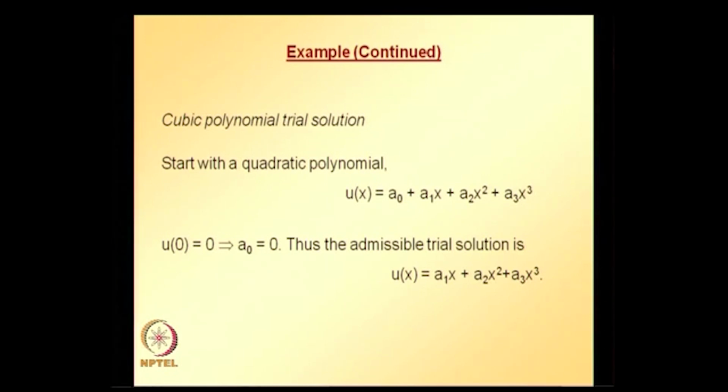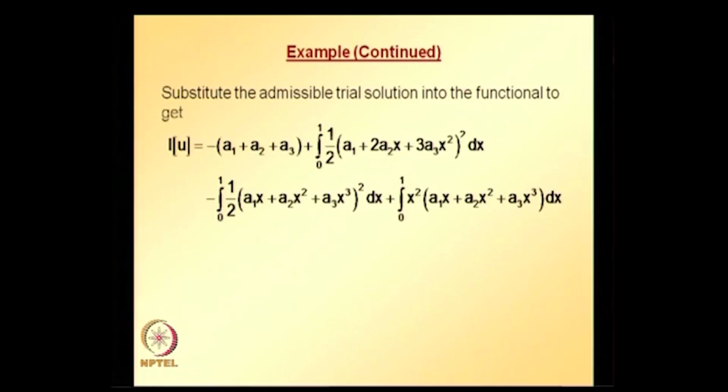Also substitute the natural boundary conditions and simplify using variational identities to bring it into the form variation of some quantity inside the bracket is equal to 0. Whatever is inside the bracket is what is called the equivalent functional. That process is the same whether you choose a cubic or a quadratic polynomial trial solution, so it is not repeated here.